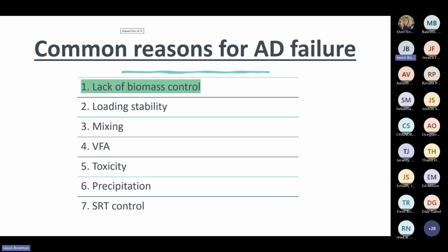So traditional systems, that is the classic CSTR style complete mix reactors, are basically an in equals out operation. That is, you have a tank that's full of waste or wastewater. For every 1 gallon that you put in, 1 gallon leaves the system. Other than the mixing and the chemical systems, there's virtually no way to actively manage the biomass concentration in these reactors. So traditional systems rely on the proper feed and chemistry up front to ensure sufficient biomass develops.